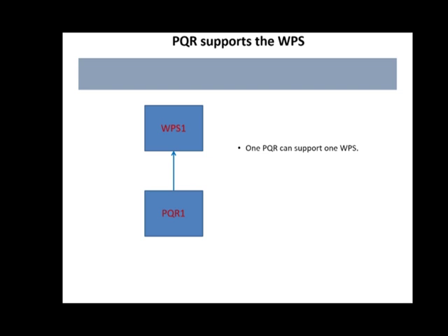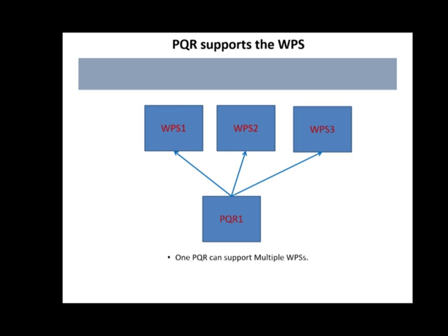And here's our supporting documentation that said we did it once, and we did a bunch of testing that proves that, yes, we can get the tensile strengths, and we've got the required ductility, and we don't have any problems, and there's no defects in the weld. So one PQR can support one WPS. One PQR can support multiple WPSs.